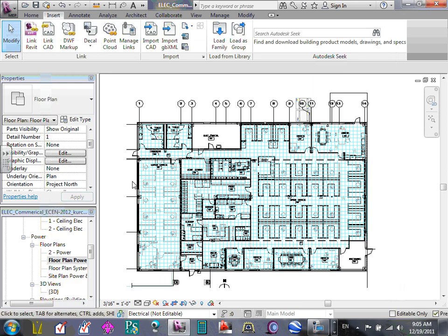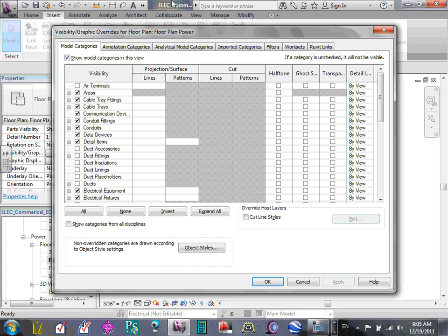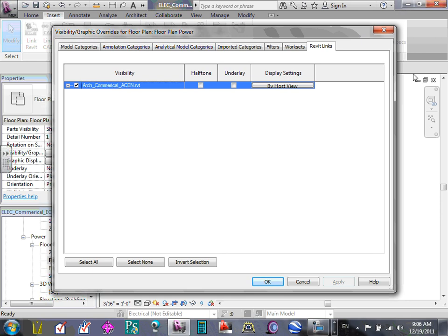One more time. I want you guys to go VV, please. Everybody can see this view. When you go there, there are a few things, guys, you have to know. Linked files. The file that you're linking, the architectural file, should be here. Don't mess with it. This is where you put the architectural file. You can do a lot of damage here.